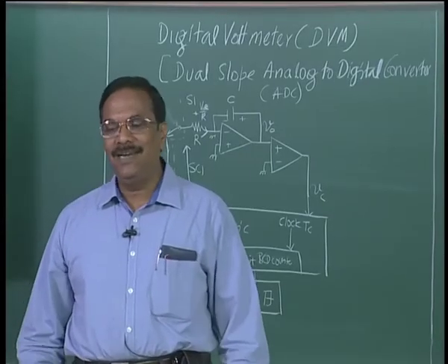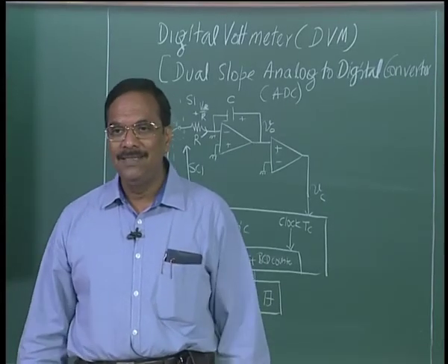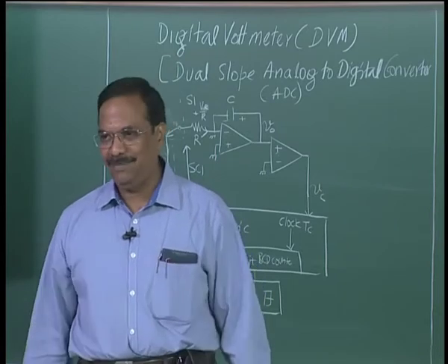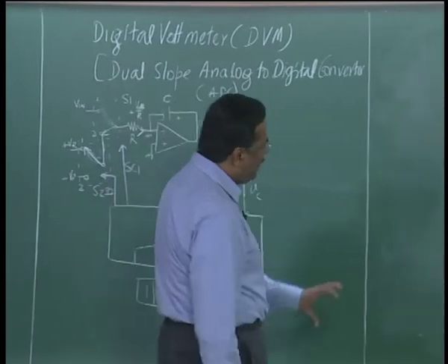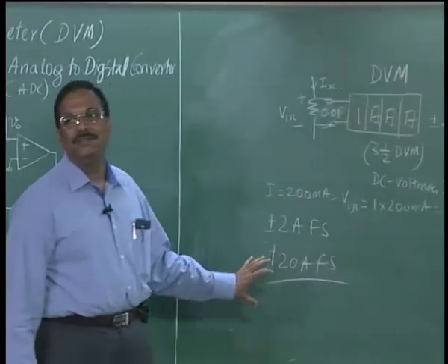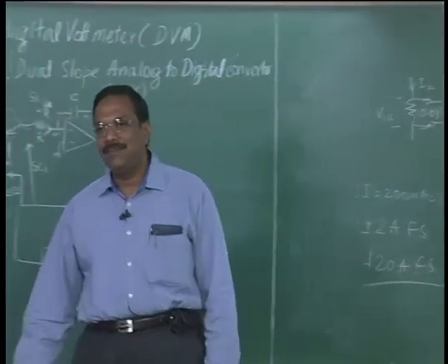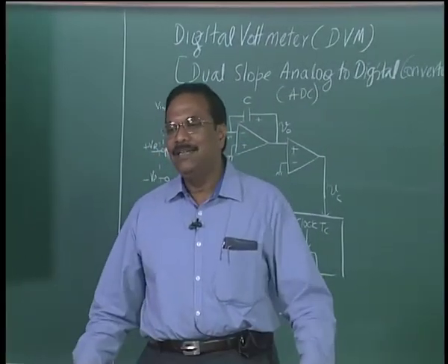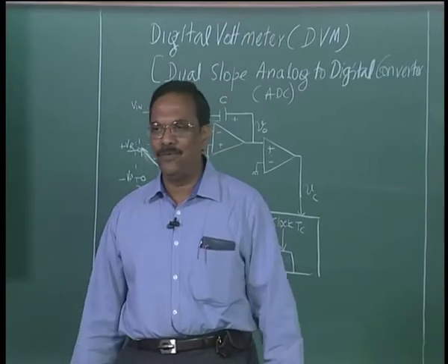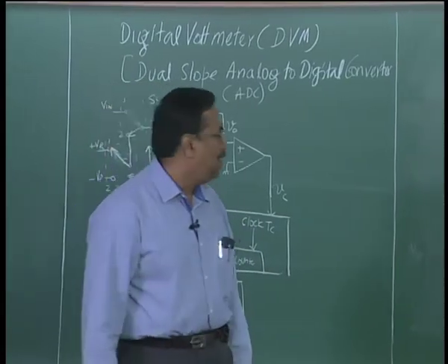4 watts is too much power, right? It will really heat up the meter. Generally you will not see this on quite a large number of multimeters. Some manufacturers give you, but those meters will be large in size and they have a really big resistor which can dissipate 4 watts, right,